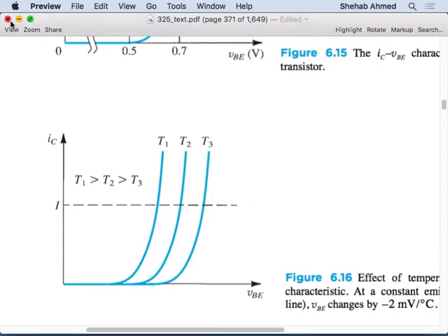These devices, not the case. This one gets hot, so it allows more current to go through. More current means more power loss, and more power loss means getting hotter. So it's like a positive feedback. It's going to burn itself, right? So that's why MOSFETs are actually quite a bit utilized in higher temperature applications.